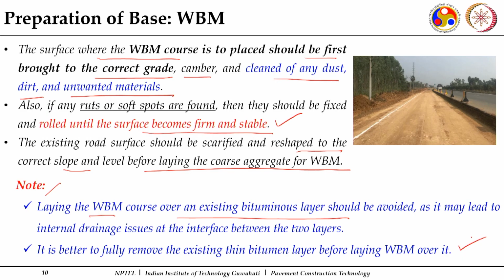So, if you have a thin bituminous surfacing, which is normally there for rural roads or low volume roads, it is always preferred that you remove that thin wearing course, because you are doing strengthening, and the surface might already have shown some distresses. So, better to remove that thin bituminous surfacing and then construct your waterborne macadam over it.